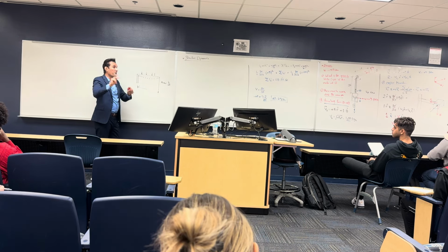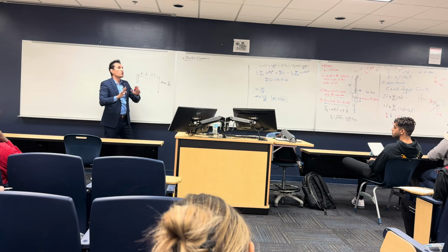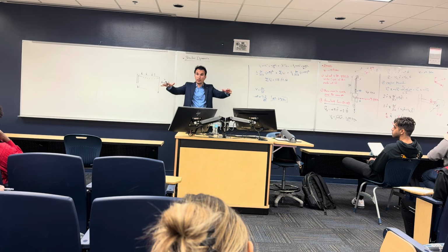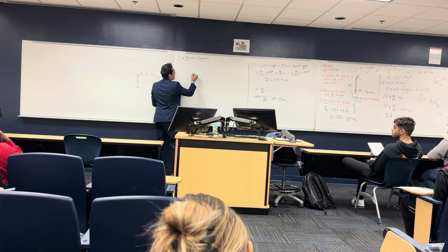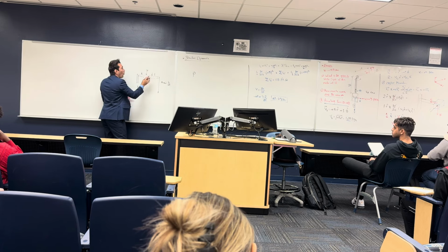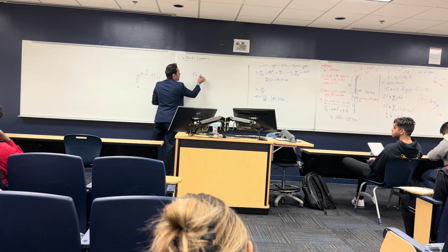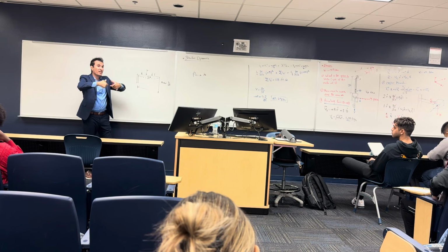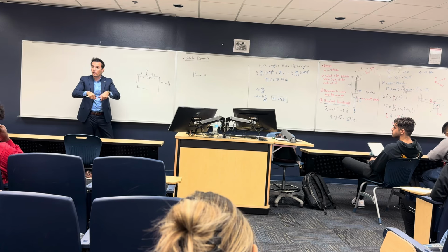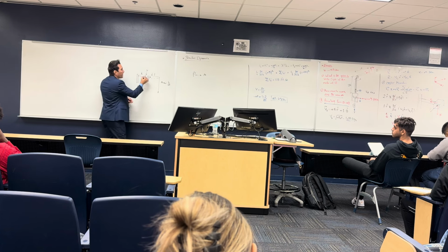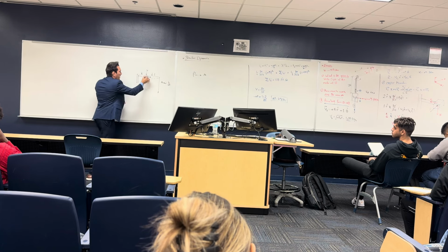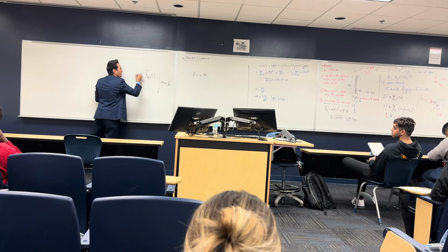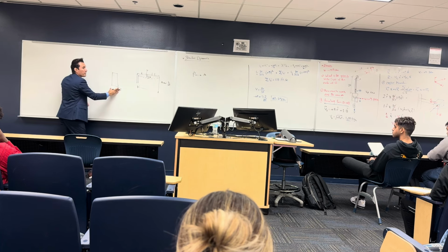So those are the two things we need to care about, displacement and forces. But let's go through what happens to the structure step by step. First, we have our structure and we put the loads, let's say loads B. The structure is going to have a deflection, delta. Once this delta happens, the structural member is going to have strain, because there is displacement. Let's say this is a beam in 3D, and if I take a cross section, it looks something like this.